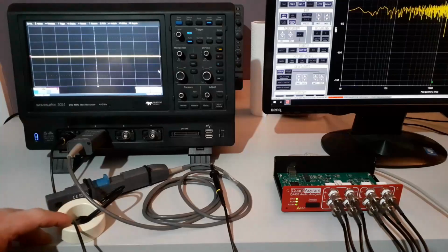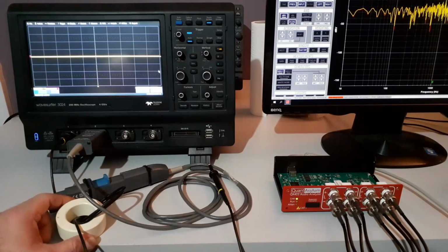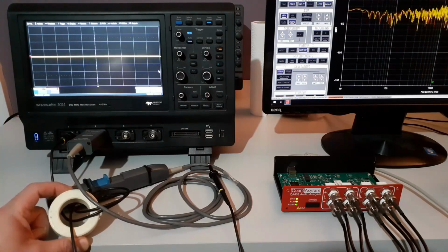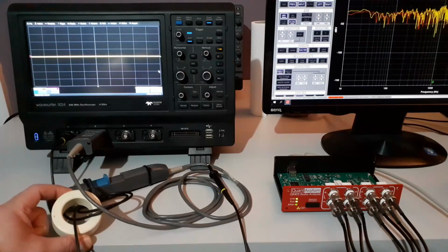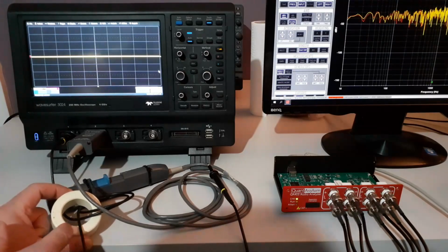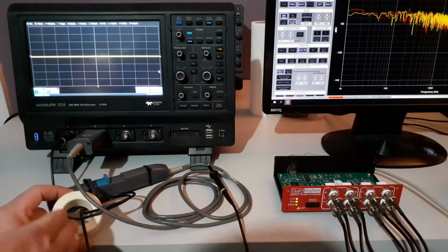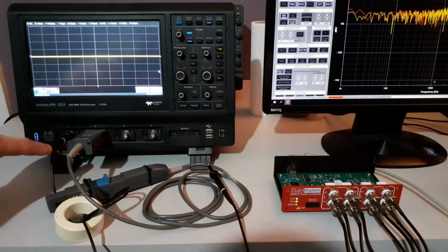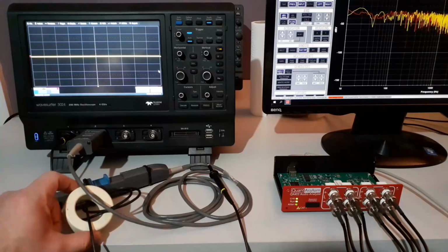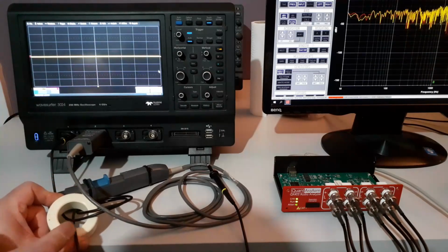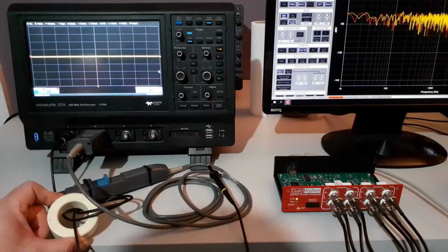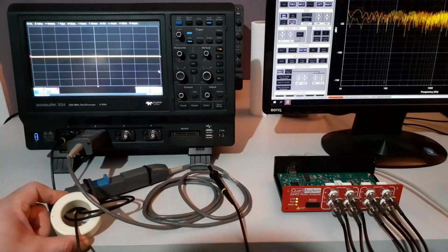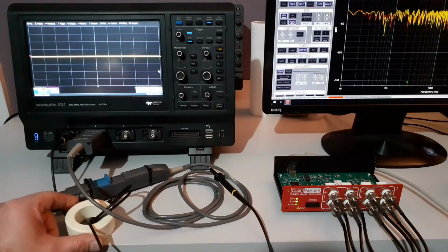And the second thing: this is approximately a 13,000 AL factor, high permeability, ungapped ferrite toroidal core, and I did 3 turns. This is approximately a 118 microhenry common mode balance choke. This is very important for filtering high frequency common mode noises. This is the second important detail.